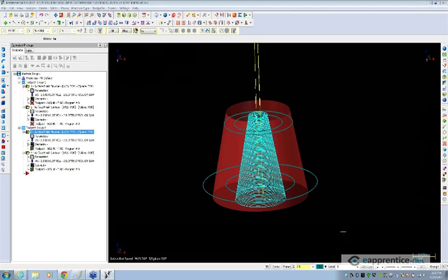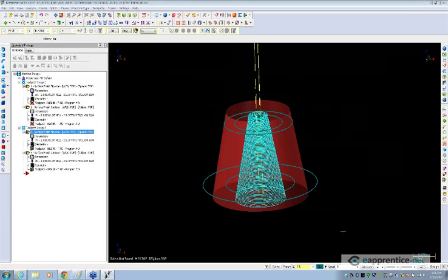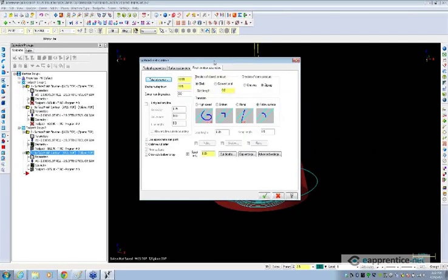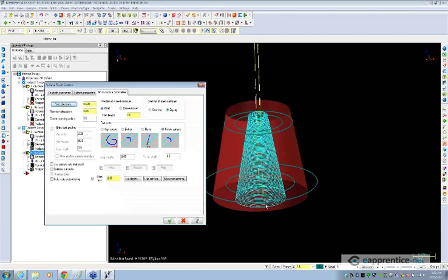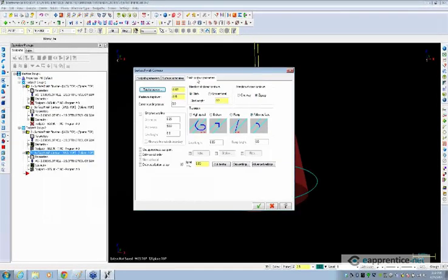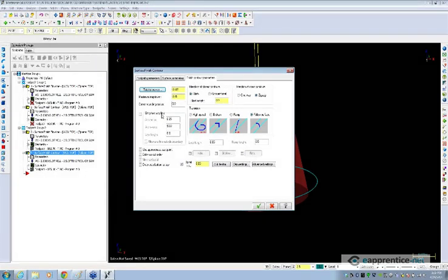Mm-hmm. And let's go. Got a question from Alan. Why doesn't the contour use the lead in and lead out, or the entry and exit arc line? Well, it is certainly possible to use the entry and exit arc. In this case, I don't think it really makes sense just based on this particular surface. In this case, I would prefer to just use the direction to get the tool into and out of the cut. But we will see that with Surface Finish Contour, we can support using this entry and exit option in order to do the cut. So we'll see that on the next part that we're going to be looking at.